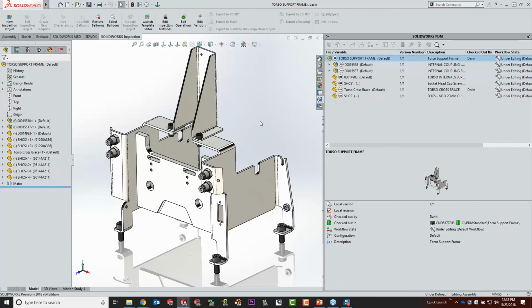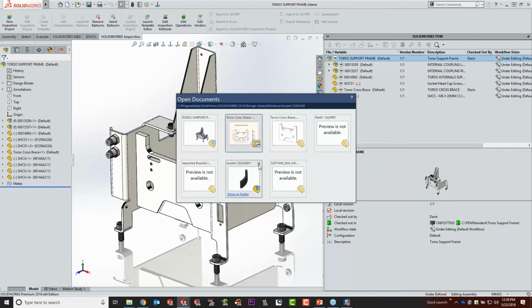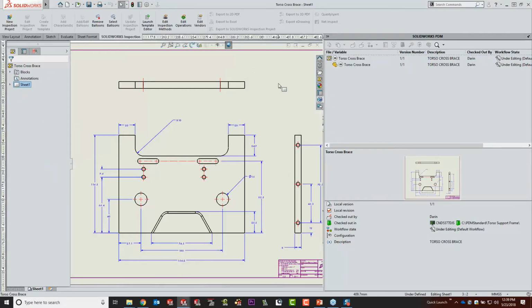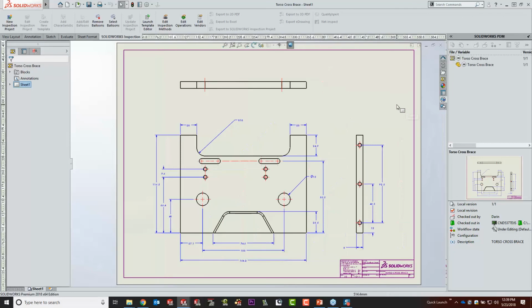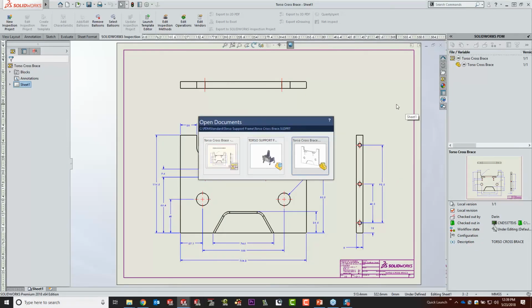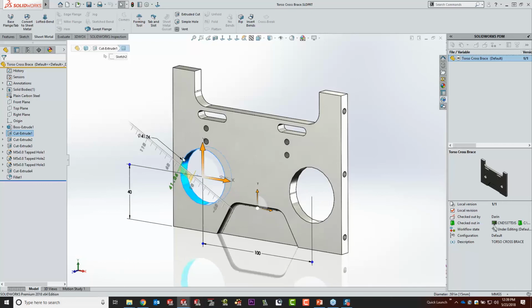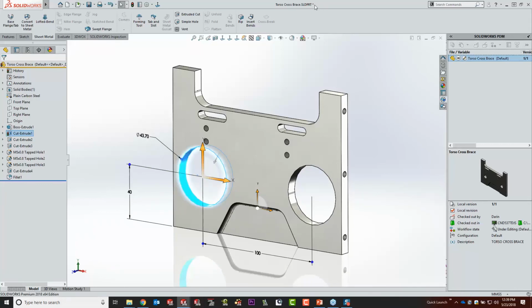Now, because we're talking about data management and control, we're talking about change management. And because of SolidWorks methodologies, let me get rid of a few of these other files just so that we don't confuse the issue. But when we're dealing with regular SolidWorks methodologies, what we're talking about in all instances here is the trickle effect of change. Now with SolidWorks, of course, we're fully associative. So when I decide to make a change to a part file, for example, a few different things will happen here. That part file becomes dirty, which now shows here an indication of a pencil in my tree.